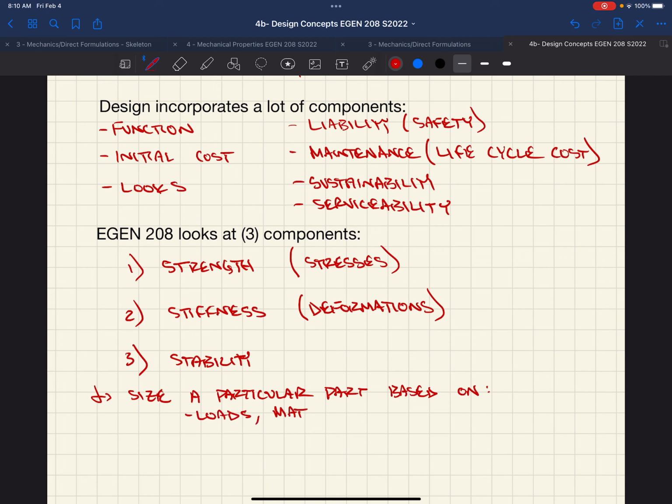I'm biased because I'm a civil, and so I know a lot about buildings, right? So when you design rafters and a roof system, okay? In this one we've got this acoustical ceiling tile inlay, right? All of these wrapped tan things are likely beams, spanning over here. So if these beams are wrapped in, say, some sort of gypsum board or stucco, the code gives us different deflection tolerances for what those elements can deflect between wall to wall in order to not degrade the actual finishes on that beam, okay? So they give that in a span ratio, right? So it might be L over 360.